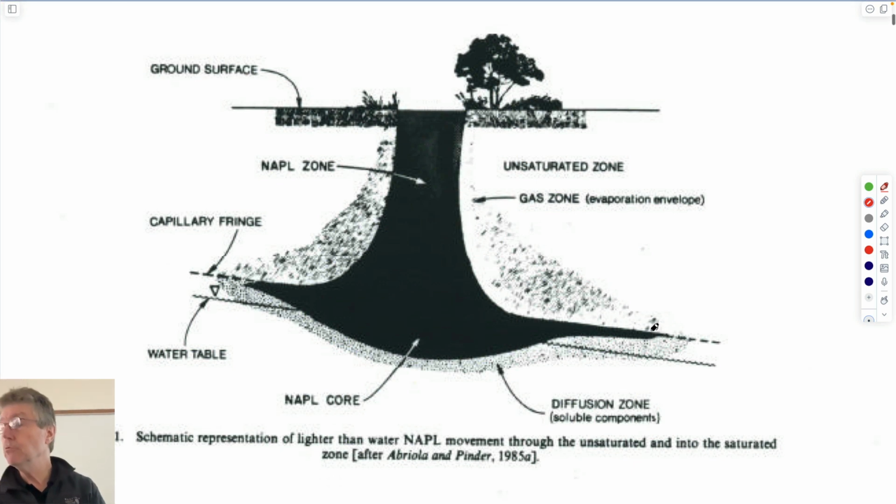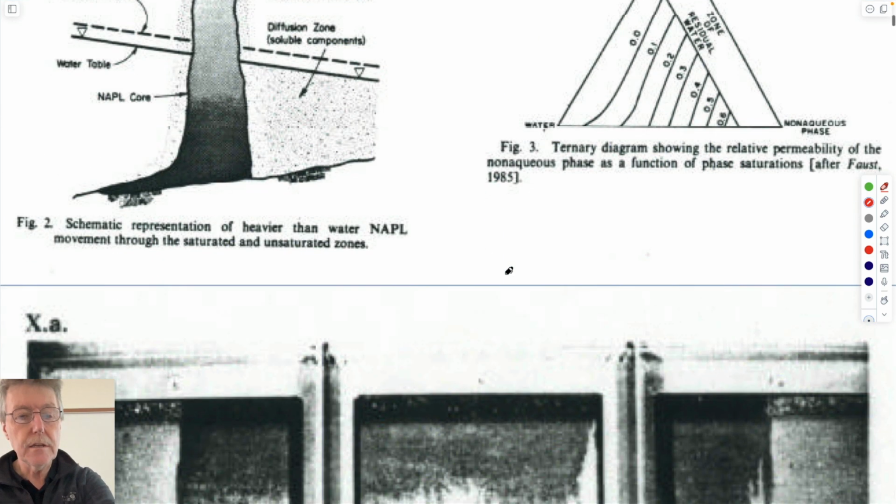So contaminant hydrology would be the mechanism by which breached radioactive waste from these containers gets carried downstream, down gradient in the subsurface by the motion of the groundwater flow. So that's your first assignment. You'll get to calculate how quickly it will arrive at this compliance point downstream, and in what concentrations we'd expect it to arrive as well. So that is one thing.